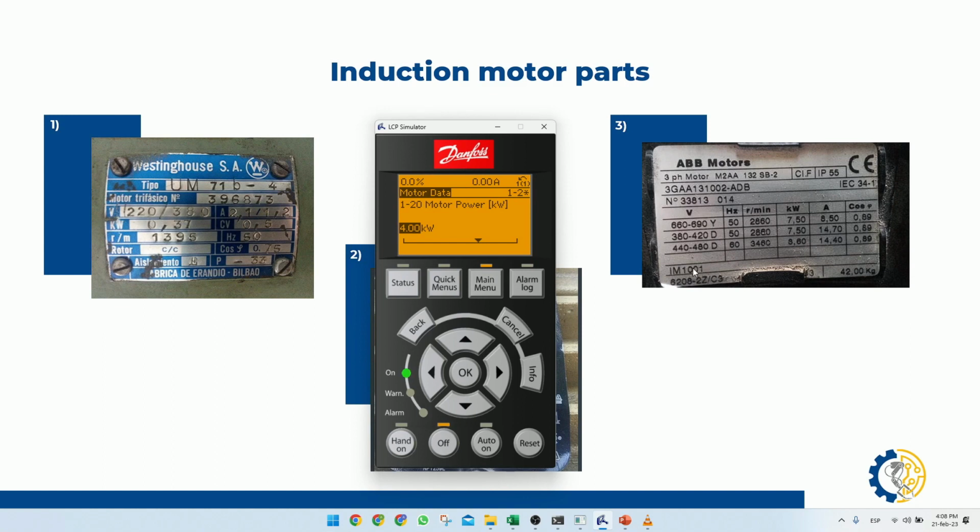It's telling me that if I wish for the first option, I need to have a star connection, and then I should enter 7.50 kilowatts. Actually, our max is 5.5, and our minimum is 1.5 kilowatts, 1.10 actually. So we're going to find a different one here.